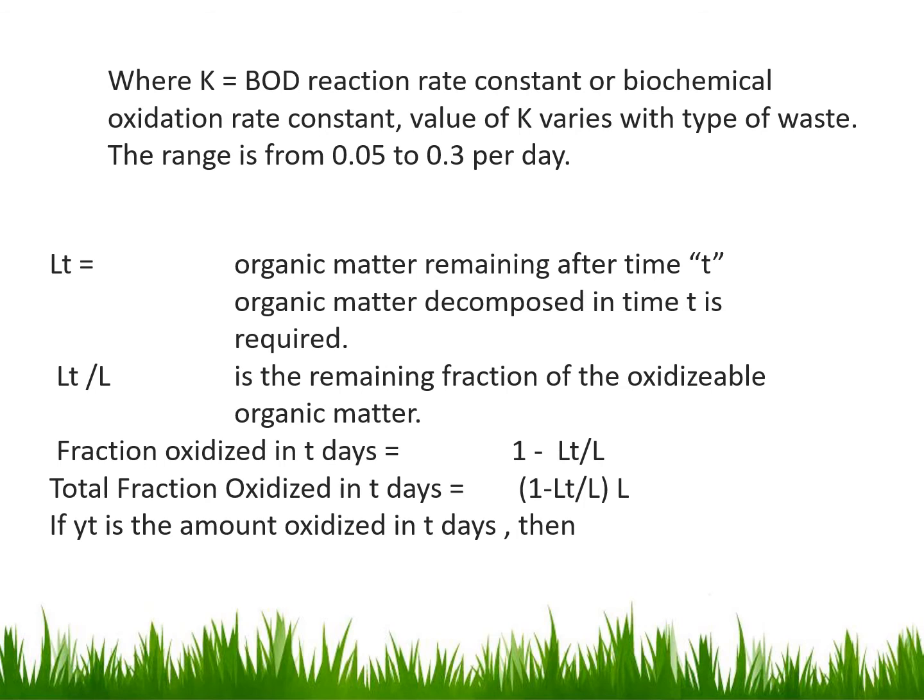So this is the organic matter still remaining, and this is the total BOD level. If we take the ratio of both, it will give us the amount of waste which is still remaining. This is the remaining fraction of the oxidizable organic matter.